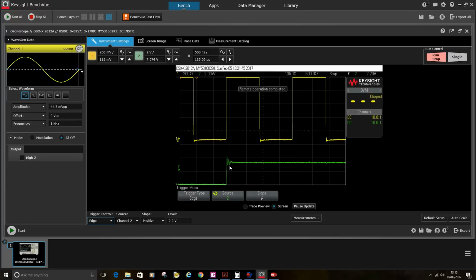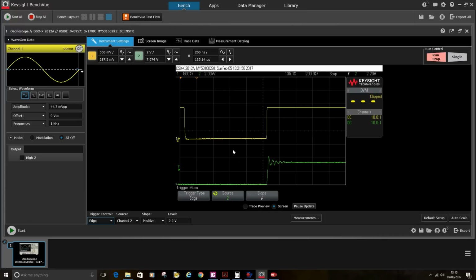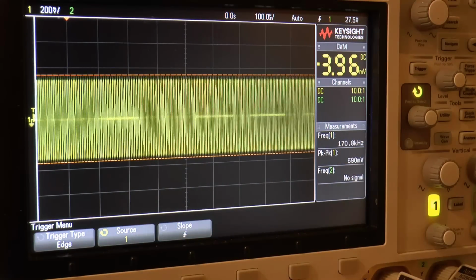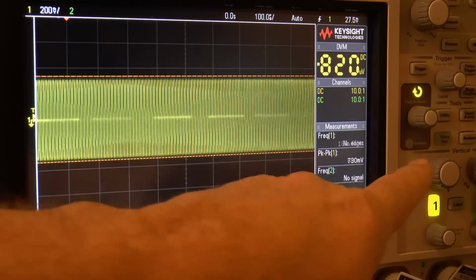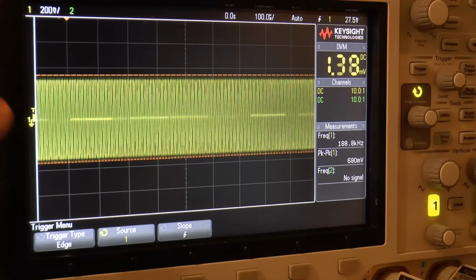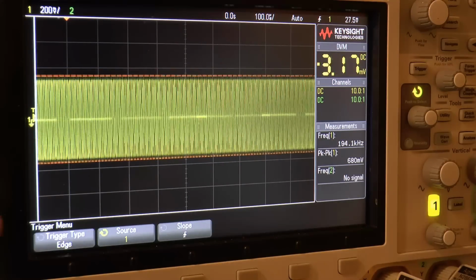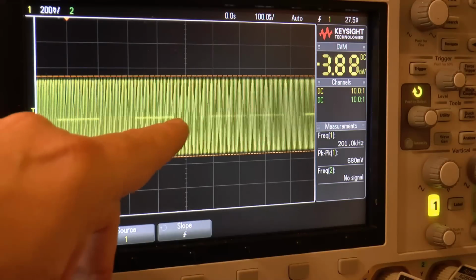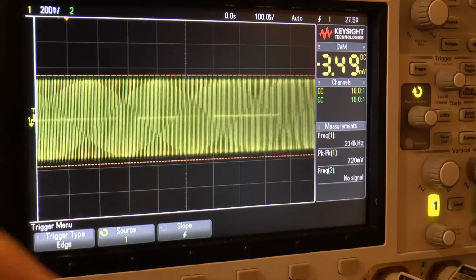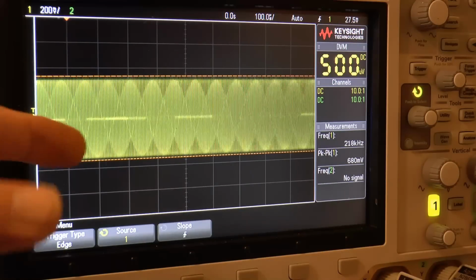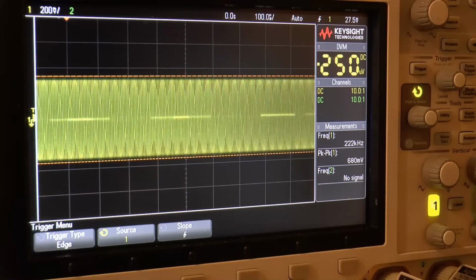And my analog device started working. You can see no delay. We're on 200 nanoseconds, no delay, and that's it. This, as I say, this analog device started running. And there's another look at the waveform generator running up quickly. We're up at 778 kilohertz. So these lines, because this screen updates at 50,000 times a second, this is actually the data being written. So you lose the data. It takes 7 clock cycles for the program to update. So you don't get a waveform for 7 clock cycles of the 25 megs.